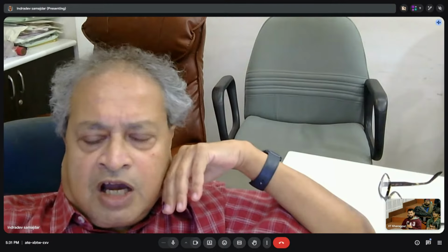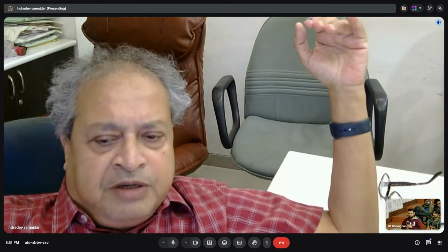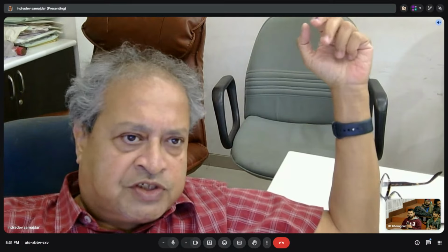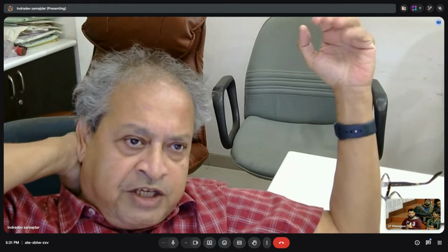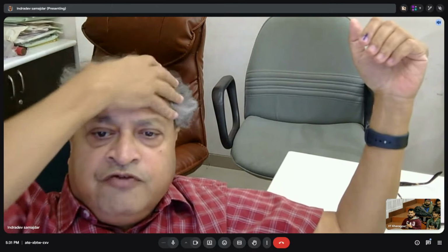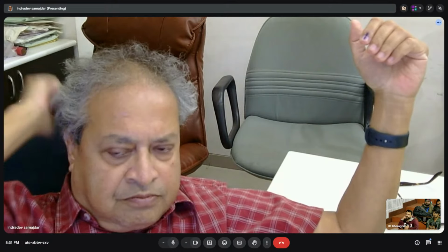Let me go to the slide. We have been using, at one time, Vijay's papers and others, Williamson-Hull, but not too happy. We have been measuring dislocation density in two ways: variance, where you take all the peaks and do a scaling, or individual peaks, where you look at the profile of the peak.